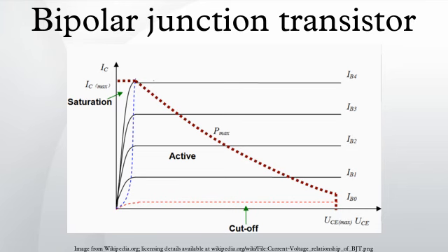The collector-base junction is reverse biased, and so little electron injection occurs from the collector to the base, but electrons that diffuse through the base towards the collector are swept into the collector by the electric field in the depletion region of the collector-base junction. The thin shared base and asymmetric collector-emitter doping is what differentiates a bipolar transistor from two separate and oppositely biased diodes connected in series.